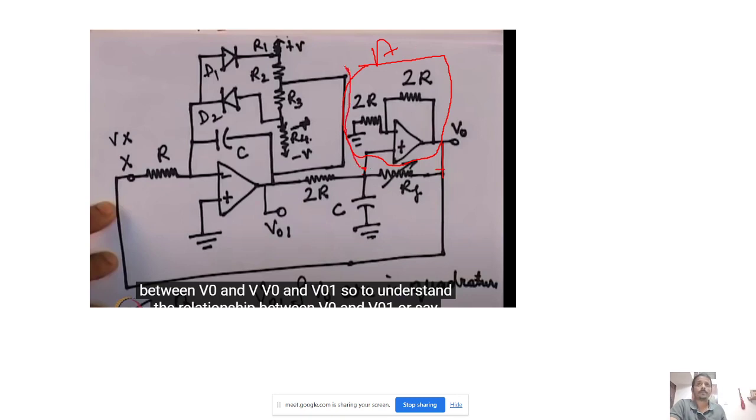Okay. So I think at some frequency, these components will provide a 360-degree phase shift here, since this is actually a non-inverting amplifier, and this entire loop will create a 360-degree phase shift.